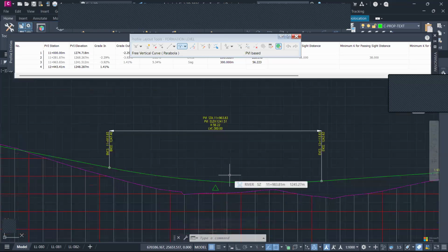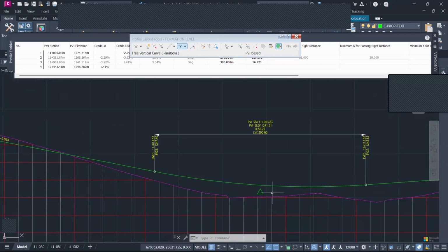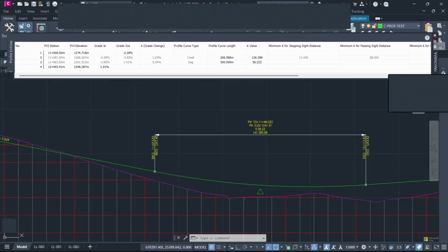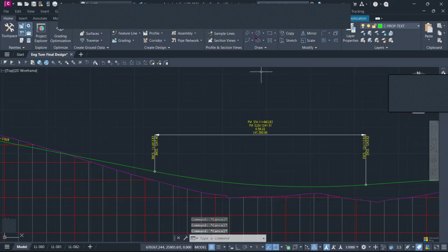There is the aspect of drainage again. The gradient takes care of the drainage. But should we also be able to position our culvert at this point? There is what we call the overburden that you account for. So the rule of thumb again, the overburden should be 0.6. So let me give you a simple demonstration here.